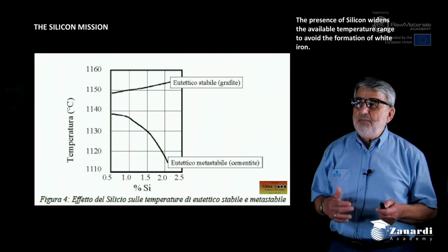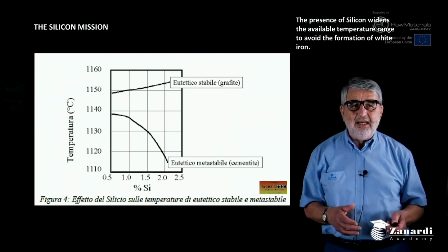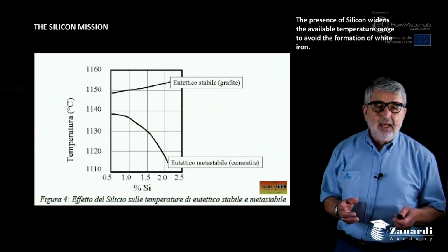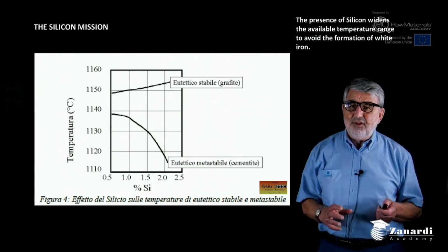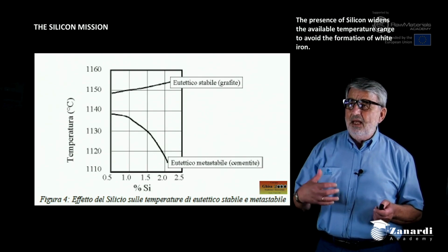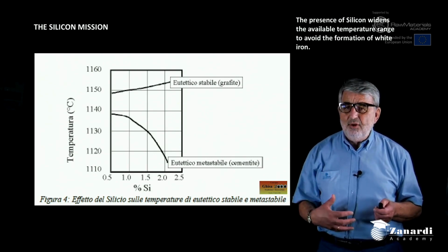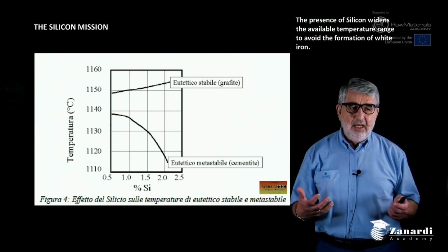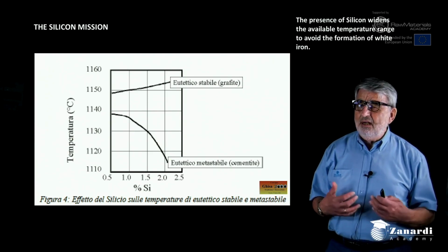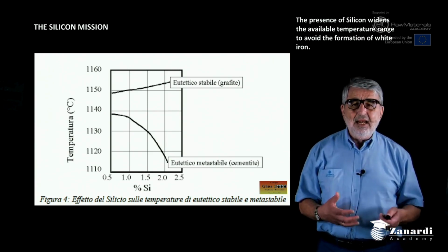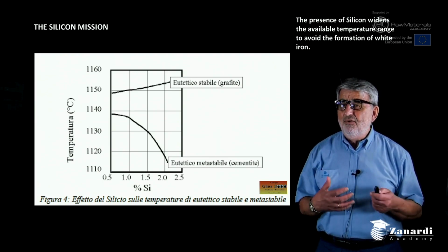So typically iron and carbon are also added with silicon. Silicon is an element that increases the activity of carbon. In this way, during the freezing process, carbon is able to escape from the iron combination, so avoiding the formation of carbides and promoting the formation of free graphite.